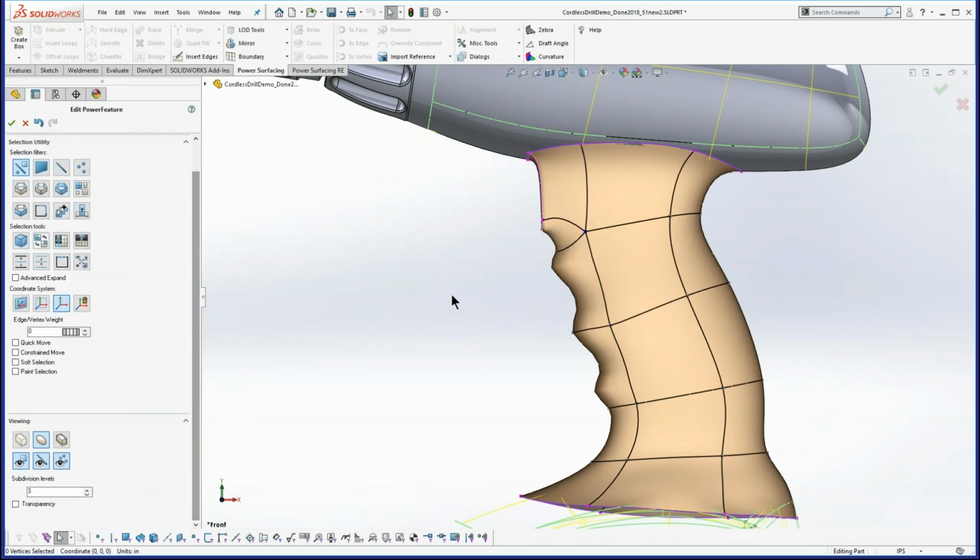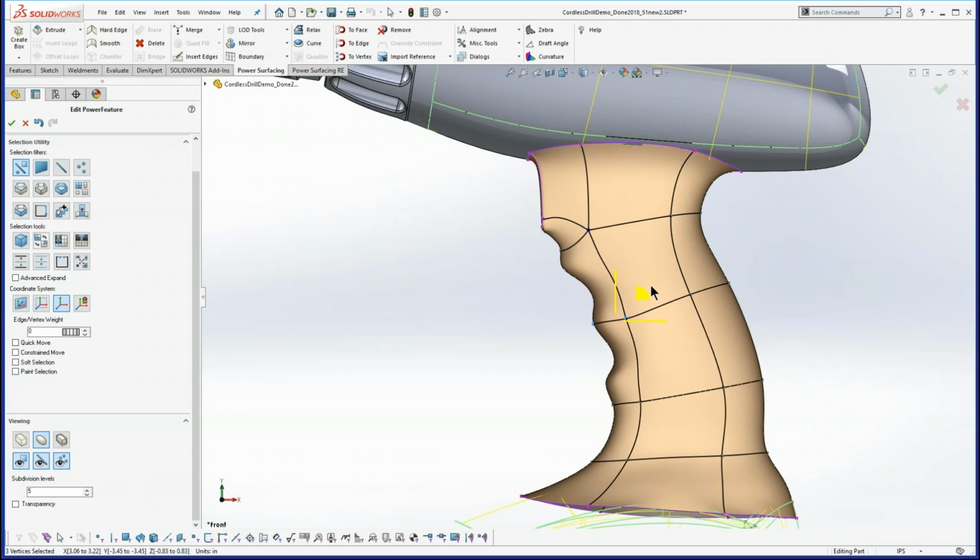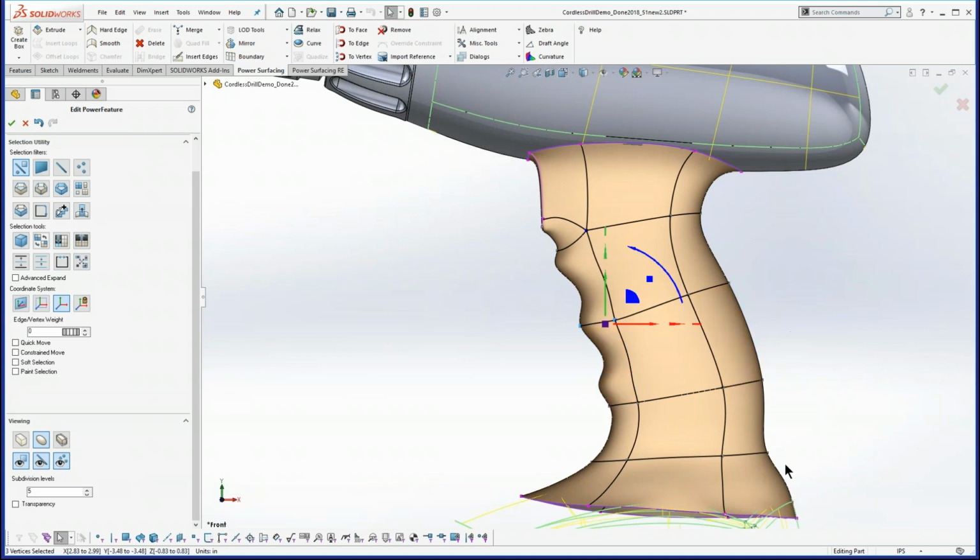And it's looking a little chunky because I do need to see a few more subdivisions in the viewport, so I'm going to crank those up a little. But now watch what we can do. We can take this guy, and the stuff that was done in level of detail in a different level tries its best to retain its offset from the original. So that's a pretty nice way to be able to model. You could still have control over the smooth, larger shape, but yet you can add more detail like this.